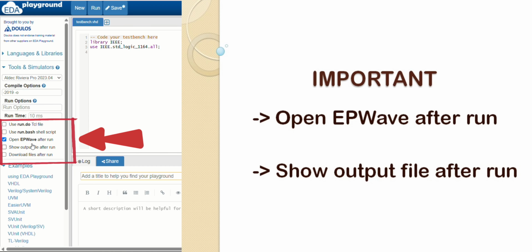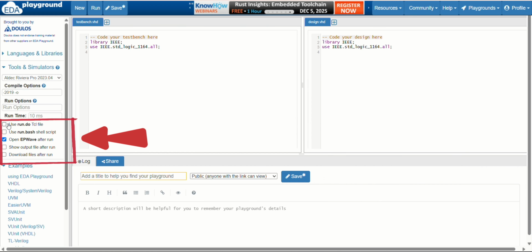So the open EPWave after run, you have to always check it, and the optional one is show output file after run. So for now, for your testing, always click on the box that is open EPWave after run.